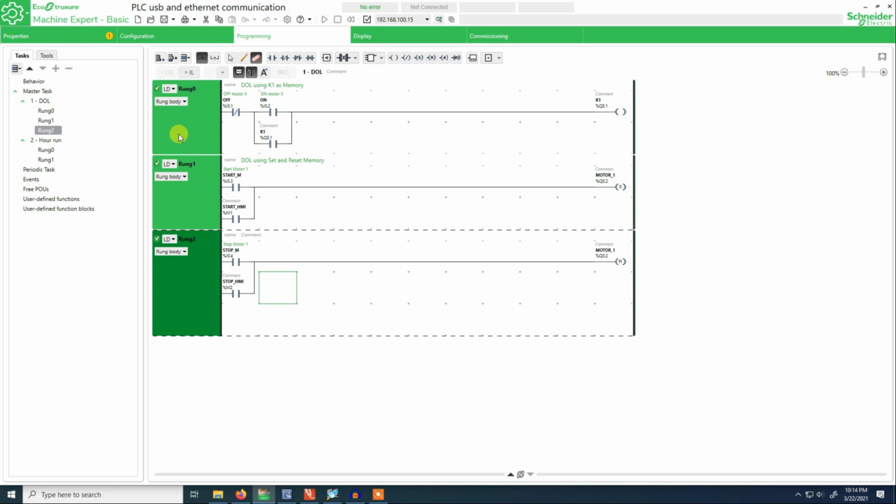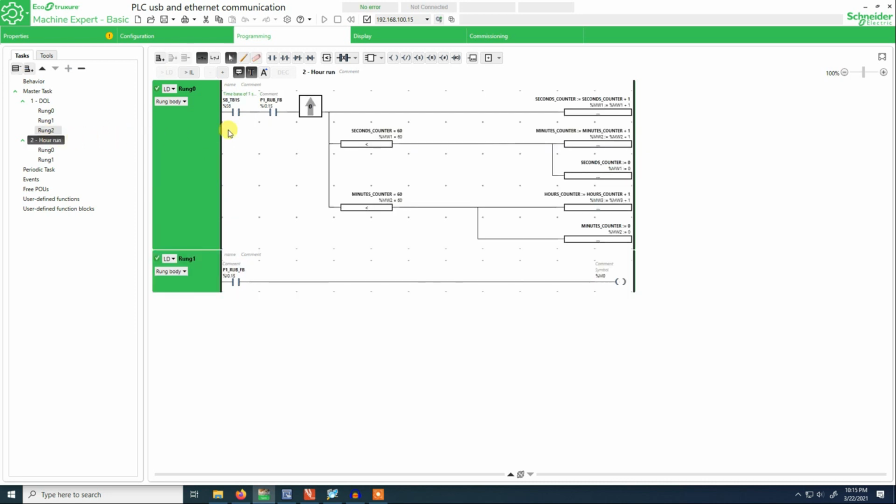So for this, here it will be 15. To have the feedback, we'll just take the feedback from the relay that is activated. Here it's connected to address 15. This will write to memory address 0. So from this we can know whenever the pump is running using the feedback which is here. So we can just save it.